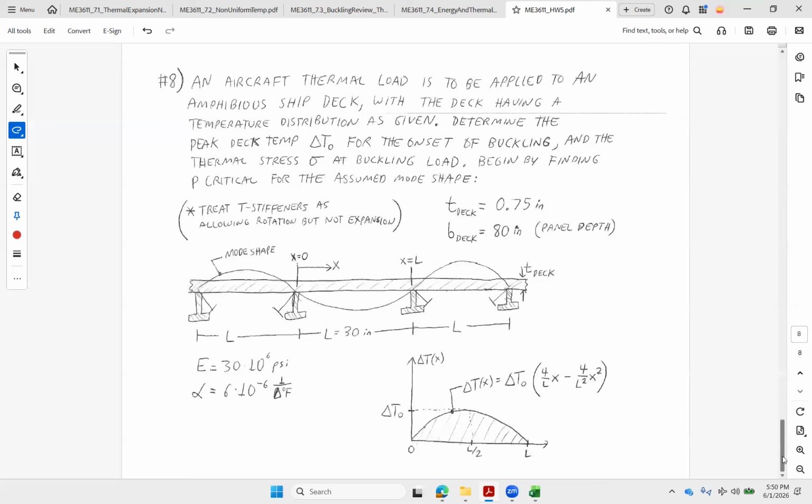And then our last problem, we're going to think about an aircraft like a V-22 or F-35. When the engine is pointed in that vertical direction, some of the exhaust comes down and heats up the deck. And we're going to say that all happens right between two stiffeners here. So in one panel width. All right. These stiffeners are pretty good against bending. It's not going to let it move up or down, or it's certainly not side to side with that continuous deck. But T-beams are all pretty close to the centroid. So they're not super strong in torsion.